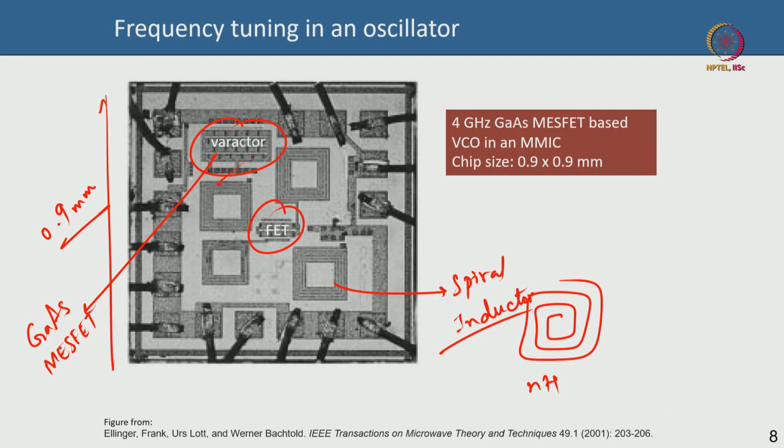Now, we have to talk about the varactor model. Because we have got an overview of the varactor and the tuning of your capacitance, we have talked about the harmonic generation, you can get 2 omega, 3 omega, etc. Those that are not desired are the idler frequencies which you have to terminate. You have to match the output accordingly at different frequencies so that you do not have extra loss, you can get better conversion efficiency. In all these cases, of course, if you are talking about a local oscillator, what matters also is how much output power you are getting. Even for a frequency multiplier, what are the power levels we are talking about? Can you get 3 omega or 4 omega or 5 omega signals, and what is the power level?